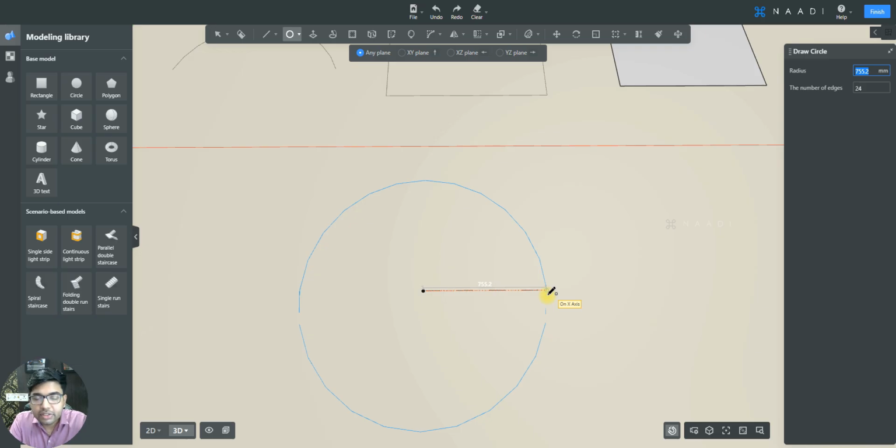That is because just like your SketchUp model, your custom model doesn't have a capability to create a curve, because both are planar modeling tools, which means they have capability to only create planes, not curves. And if you want to create a smooth curve, then you have to increase the number of edges or number of segments so that it appears to be curved.